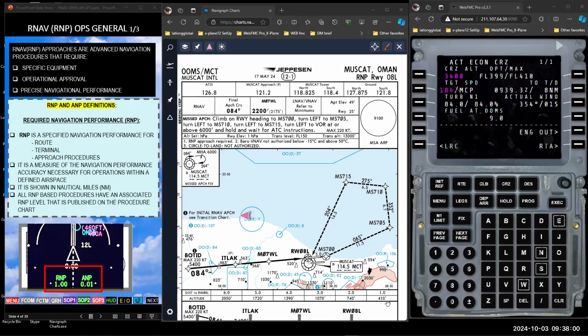What we'll do shortly is configure for flaps 5, because I'm by myself on the flight deck, and then turn to left base. Generally, you would configure to flaps 5 when on base leg. So we'll go into the simulator and view just what I've been speaking about.